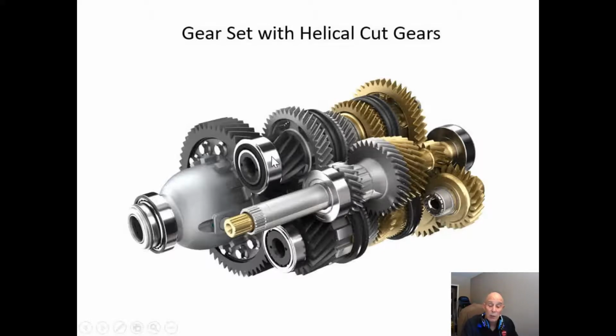Because again, if you remember back just a little while ago, we were talking about our clearance and our backlash. Now, if those bearings aren't set properly, that bearing can move, and under load it's going to push further apart, which is going to increase that clearance and move our contact point further out on the tip of the tooth. So instead of having a tooth that's in nice contact, as it starts to move out, it's putting more load on the end of the teeth. Hence, we're going to end up with a failure. That's why the first thing that's going to show up is heat. If we start getting an increase in heat, it could be because we have a bearing failure. And again, the easiest way to check for that is to pull the magnets.